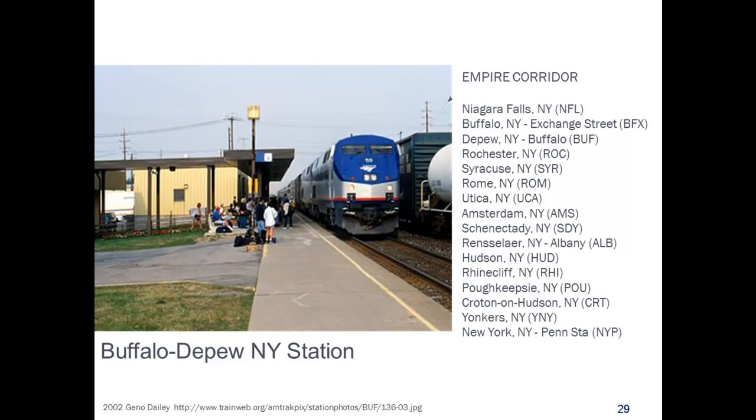Well, a fifth action that can be done, and this is frequently overlooked by many of the passenger advocates, is to add station platforms to both tracks, not just for passenger convenience, but to make good use of the railroad's existing capacity. With one platform, trains on the outside track must cross over to reach that platform. Crossing over takes time and space on the railroad, and on a heavily traveled route, crossing over can delay many trains in both directions. An example is shown in the photo.